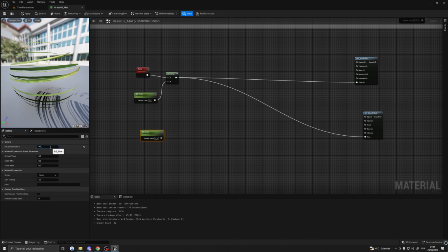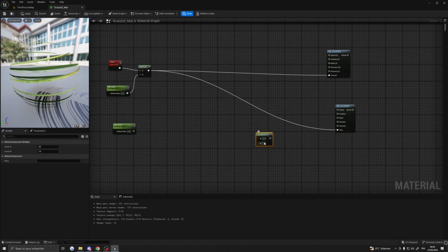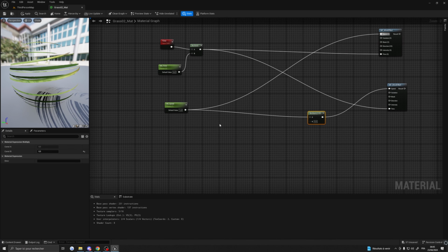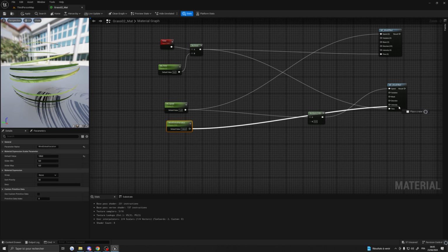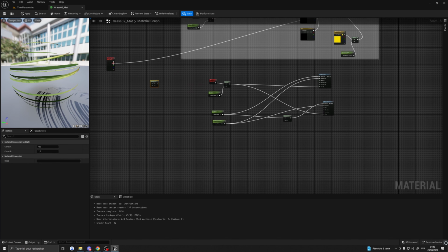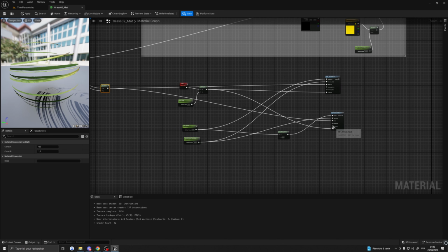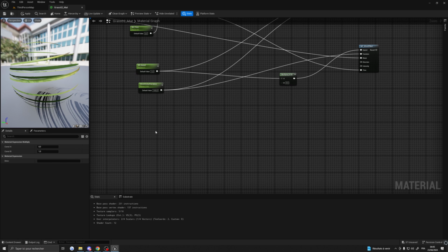I'm gonna create another parameter and name it as bs speed. Bring a multiply node, multiplying by 0.5, and one of the results into the speed and the other into the speed. Now I'm gonna bring this and name this as global variation, and this is gonna be put inside the variation. Now I'm gonna multiply both of the red vertex color and plug that into the mask.